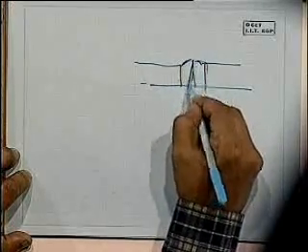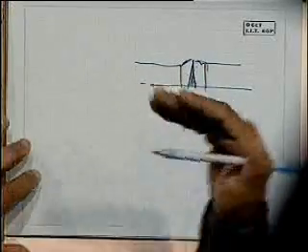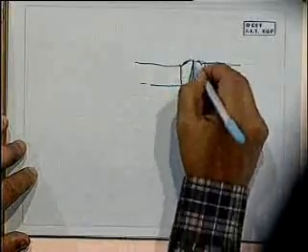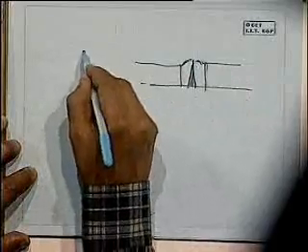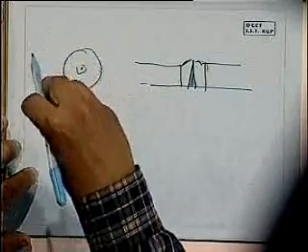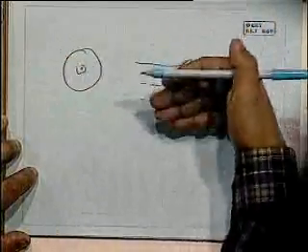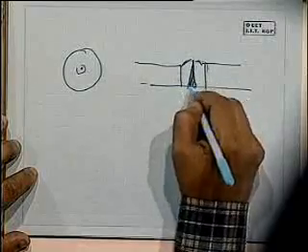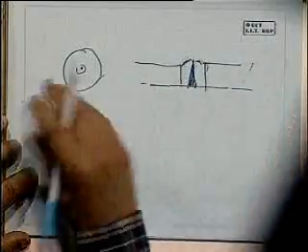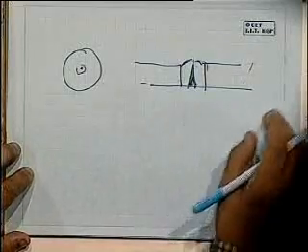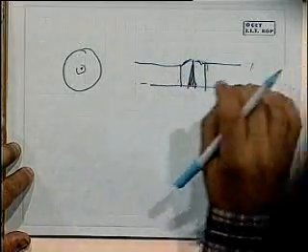Imagine this to be a sort of rounded figure. We are looking at a section of it, and there are millions of these little cavities. So in the plan view, it's simply a hole like this with a dot, or the cone coming to a tip. If you're looking from the top, what we're looking at is a cross section where we can see a cutaway, that there is an emitter tip like this that has been etched into the substrate by using electronic processing techniques. So the millions of these that are created, it's all a batch process.